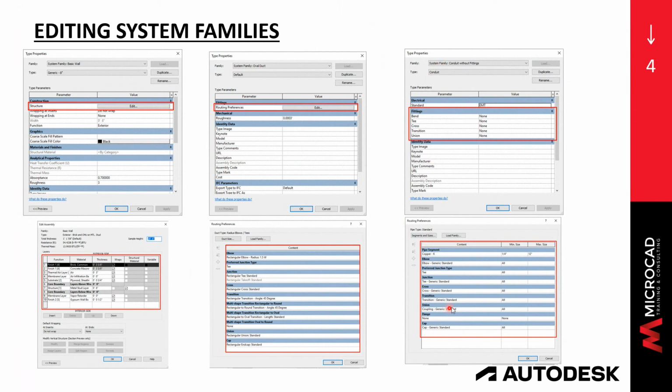the pipe families here. Pipe families are very cool because you can narrow down. So the more complex your projects go, the higher your LOD, the more you can define in your pipe system family the different junctions and the different elbows that you need. And this dialog box can be made very accurate to make it fit industry standards at a very high level of detail.